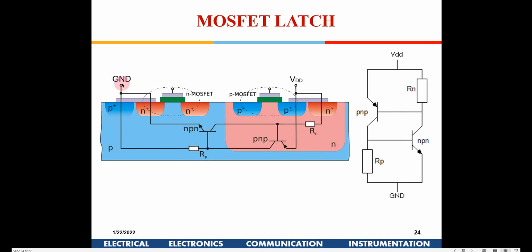And since you have connected this ground here, so within the bulk region, because it is lightly doped, you can think of having an RP here. So there will be some stray resistance here. So this is RP. Similarly, within the bulk N region you have RN out here. So that is the resistance as we move across in this region. Because this is N, not N plus, this is lightly doped, there is an RN. So you find two transistors which are connected back to back here, right?